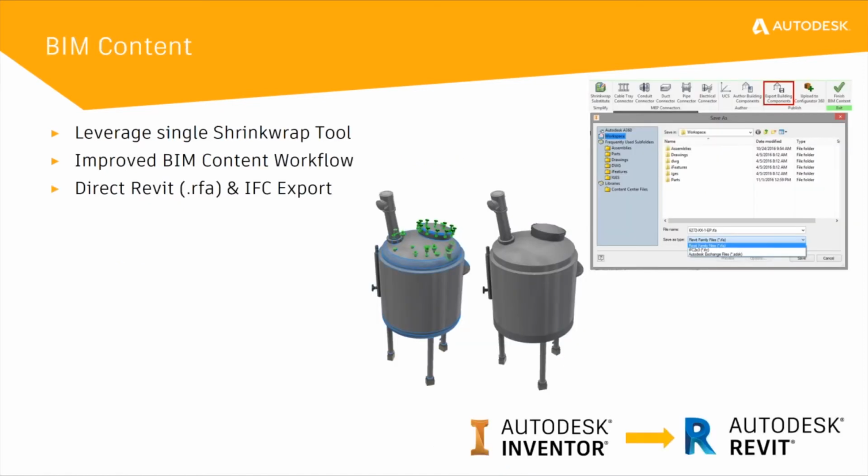That Shrinkwrap is kind of the first step in our BIM content workflow, if that's an industry you're in. So you're leveraging that same Shrinkwrap tool that's in the standard assembly toolbar, and we've improved the overall workflow, not only for authoring BIM content, but when you're done and you're exporting these building components, you can go directly to IFC or to Revit RFA format from within Inventor. So it saves you the step of going to some other third-party format to get files natively into Revit.